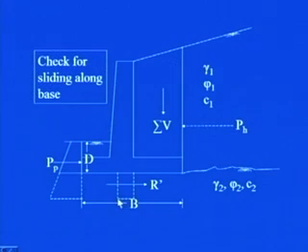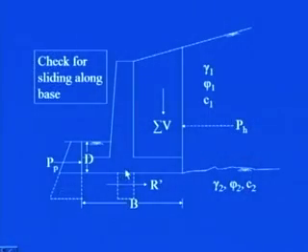You see here, this is a kind of key that is provided. It is not an additional unit during construction. What happens is that monolithic construction is done of this particular key with the base slab, so that the resistance developed is over this particular depth. With the presence of this key, when the wall pushes towards the soil, the passive force, which in the absence of this key is generated only up to a depth of d, will be developed over this larger depth if the key is provided.